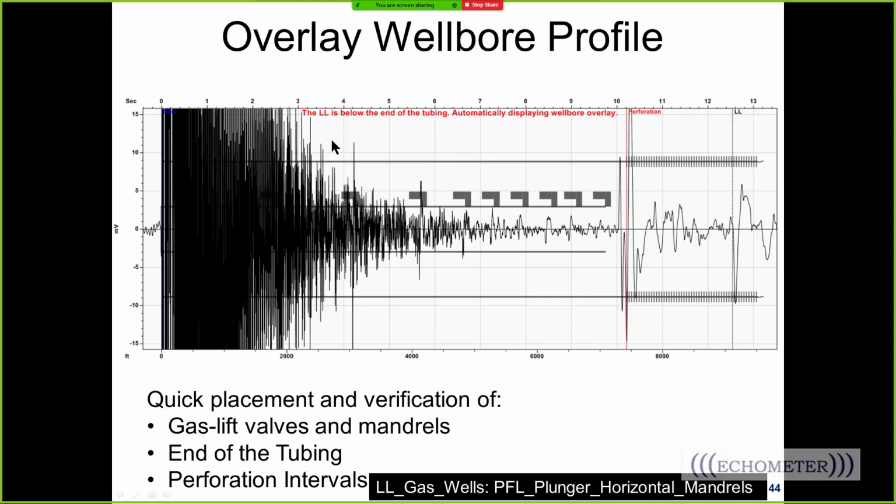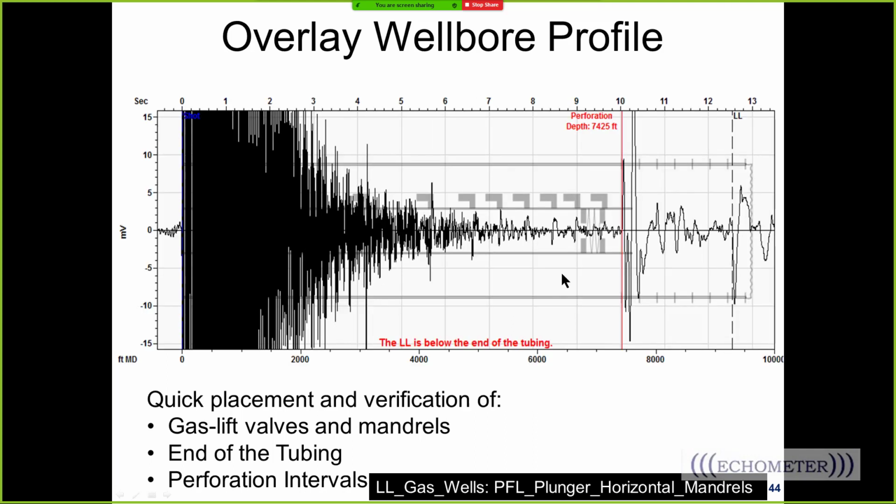And so I re-entered the well bore schematic into TAM. Now in TAM, this is the well bore schematic, and now you can see that this upkick didn't match anything before, and now it matches the top perf. And this upkick matches the end of the tubing, and this upkick matches that perf, and this upkick matches that perf, and this is the horizontal section of the well. And so this is way out in the horizontal, and we're seeing liquid level way out in the horizontal, which is common when there's not a lot of gas.